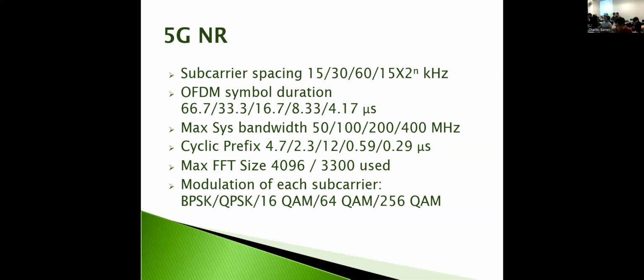And so as you look at the standard and go up from that radio level up the network stack a little bit, you'll see that there are all sorts of different things defined on how the base station and the subscriber units collaborate to communicate, right? And there are all these flexibilities, all these subcarrier spacings, these cyclic prefix lengths, and so on.